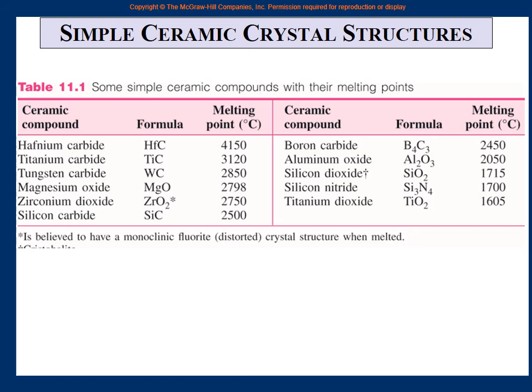Now, before going further, what is the major use of ceramics, right? We have talked so many times about how we make metals. We go to areas where iron ore is there. We do the mining. We take the iron ore, we crush it, we make it into a powder, we melt it. After melting, we do the chemical reactions and so on, and then steel is formed. But where do we melt it? If the furnace is made of steel and we want to melt iron in it, the furnace will also melt. So you have got the answer now. The furnace will be lined with ceramic. The ceramic can melt at 4000 Celsius, so it will not melt, but at 1400, 1500, 1600, all the iron and steel will be completely melted. So whenever you want to do metal industries, you do them here.